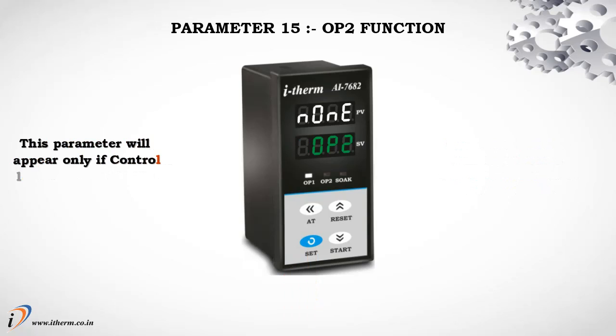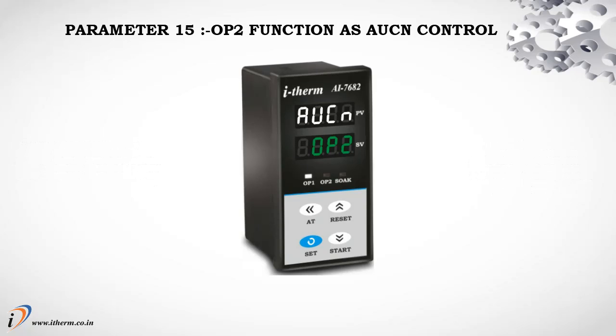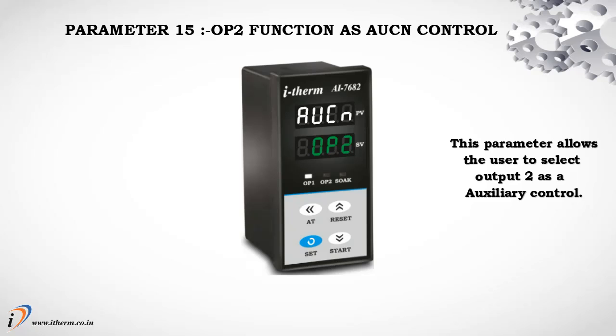Parameter 15, Output 2 function. This parameter will appear only if control logic is heat or cool. When none is selected, output 2 will be permanently deactivated. Parameter 15, Output 2 function as auxiliary control. This parameter allows the user to select output 2 as an auxiliary control.